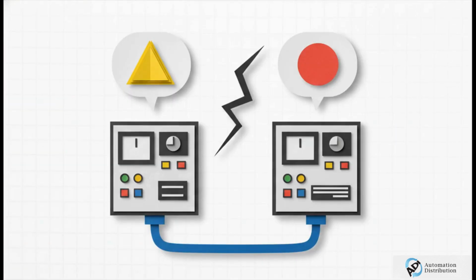But I promise you, they are not going to magically talk to each other just because they share a cable. Now, the trap people fall into here is confusing the physical wire with the application layer. Industrial Ethernet handles the vast majority of new network connections out there today. But what is actually flowing through that wire? That's the real question. The physical layer, the standard wire and those little plastic RJ45 connectors, that stuff is completely interoperable. You can plug them in anywhere. But the application layer, the way the data is actually packaged, formatted, and exchanged by the brains inside the machines, yeah, that is absolutely not interoperable out of the box.